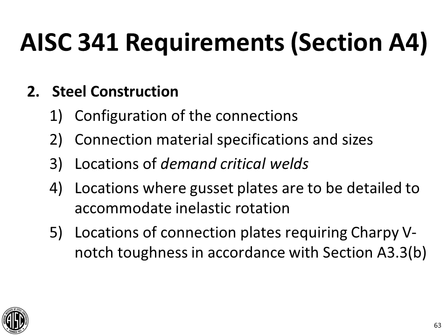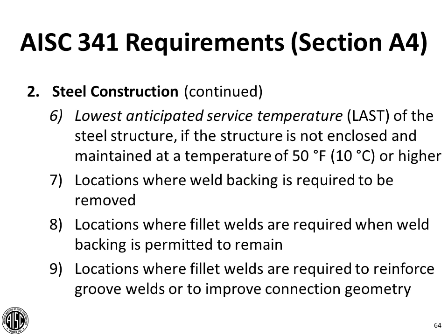And while the engineer has that prerogative, that's not, I think, a very good use of the owner's money, because not all welds need to be demand critical. And the seismic provisions are specific about the ones that they have identified that should be demand critical.